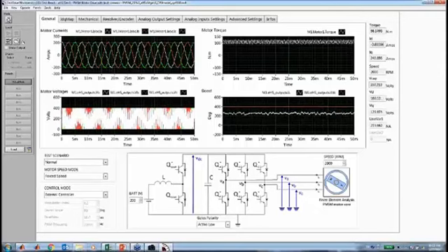All of these things, plus the compatibility with drivers, I mean, I have so many things. It's a very complete solution. All of those things allow you to increase your test coverage a lot. Compared to a dyno bench, that would be more restricted because you need to respect safety, you need to respect schedules of other teams using the dyno bench. HIL-based simulation is a lot more flexible and allows you to perform a lot more tests than you would do with the dyno bench.